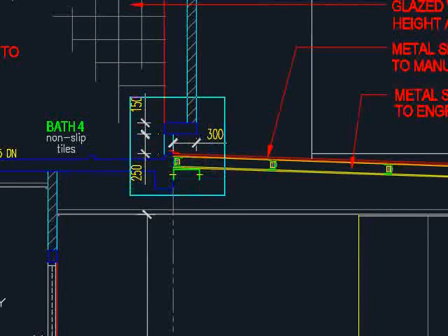Now this won't be a typical beam. You cannot rely on the brick wall here to support this horizontal concrete member. That means this again needs to come in one piece. Most likely the section will look something like this, so that it is able to support the wall here. The dimensions are given here.